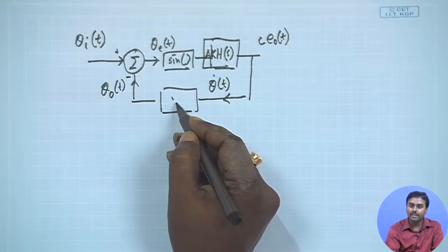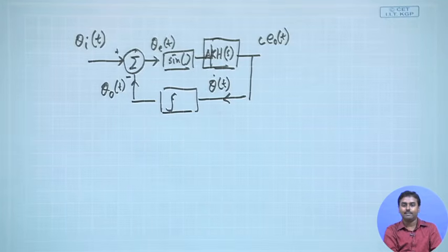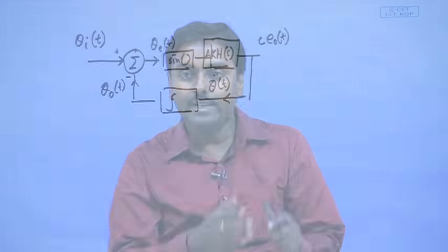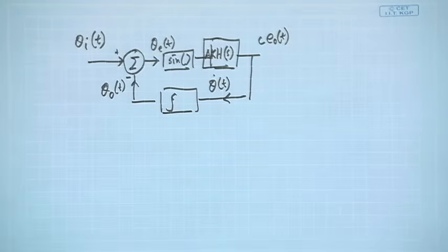So what should this circuit be? This is the integrator, that is the beauty of it. You can immediately see very nicely that the nonlinear circuit, if I visualize it from the phase perspective, I can actually transform into a linear circuit. I have an adder, I have an integrator. In the S domain this will also be treated as a linear part. H(s) is a realistic filter, so no problem in all these things. The only problematic thing is this sinusoidal.